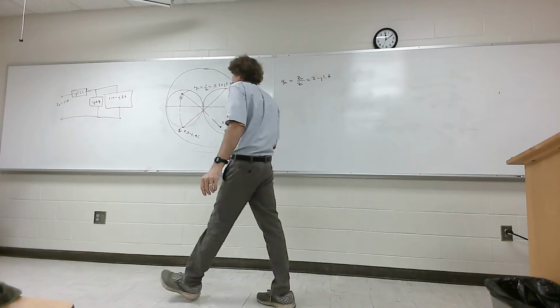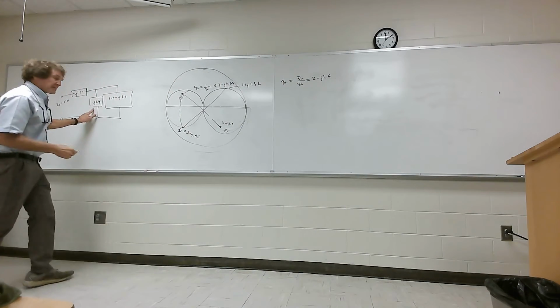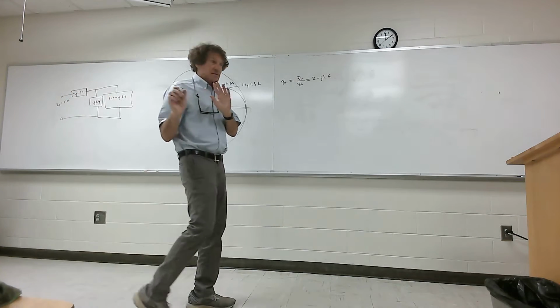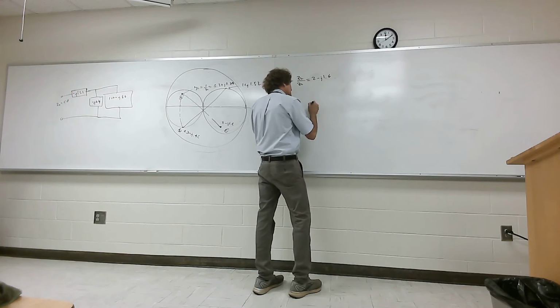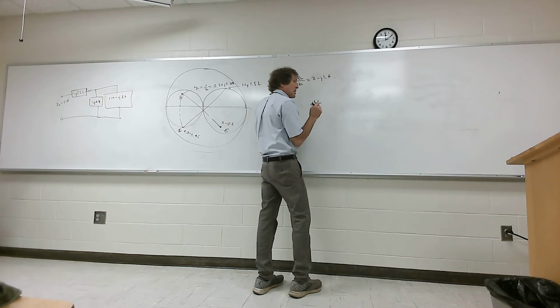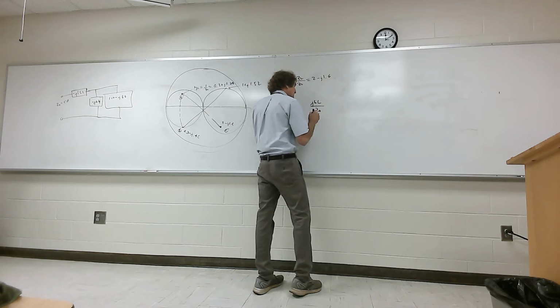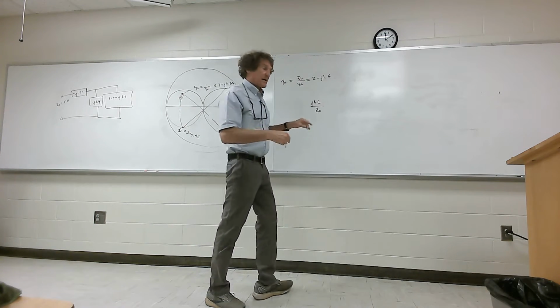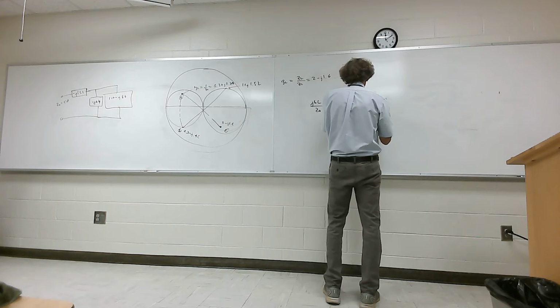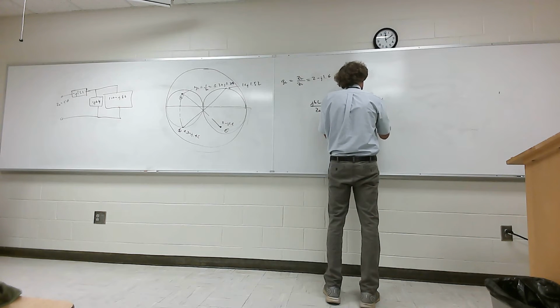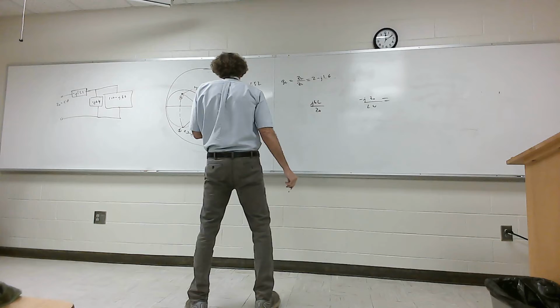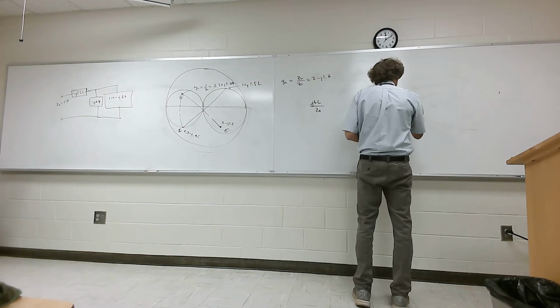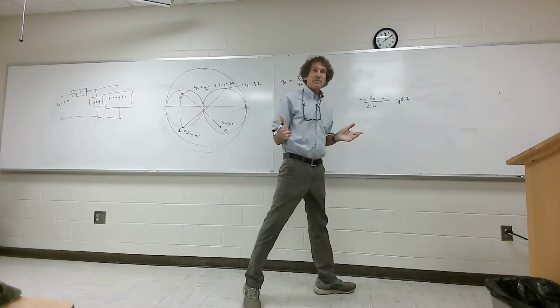Now I'm going to get the value of this, right? And that is an admittance, correct, class? It's in parallel. So for inductive reactance, it's J omega L. When it's normalized, it's omega L divided by Z0. That's the normalized inductive reactance. Take 1 over that, and I get the inductive admittance. So I have Z0 over omega L with minus J, and that's going to be equal to minus J 0.7. Does everybody follow me?